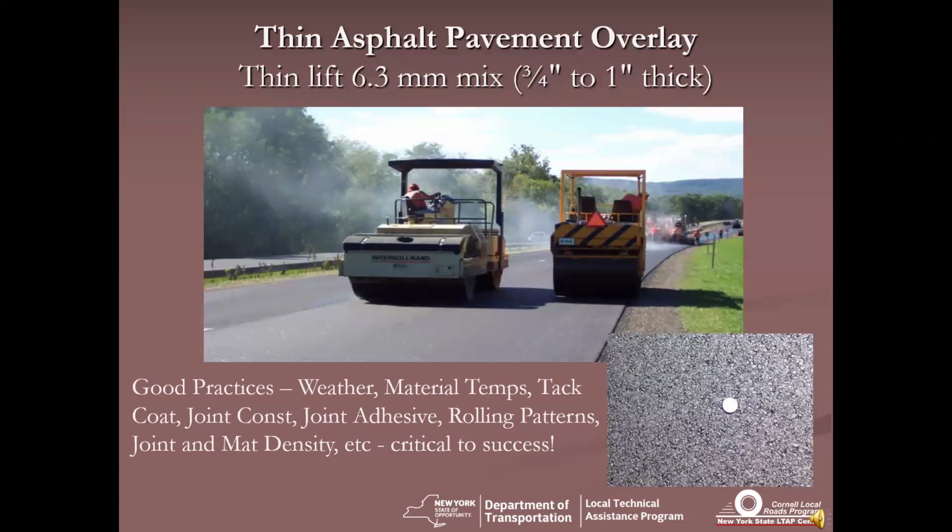You've got to be paying attention. It's got to be good weather. You've got to be watching your material temps. You've got to be using tack coat and joint adhesive. You've got to be paying close attention to your joint construction, your rolling patterns, your joint and mat density. All of those are critical to making that succeed. But if you do it right, it's a great product.